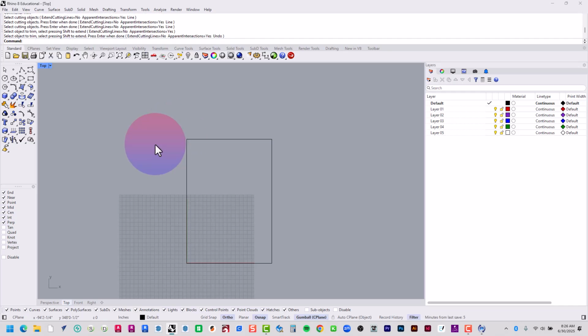Now we're going to give this a little bit of thickness. Since we don't exactly know the thickness of these walls, we're just going to assume. If I look at Albert's model, he went about 7 inches. We can guess something like 6 inches, although it's probably way thicker than that. So I'm going to use the offset command. The distance, I can type in D for distance, is going to be 6 inches.